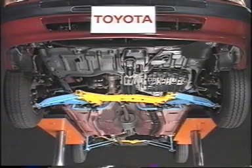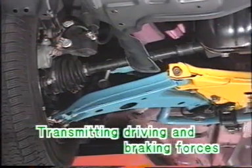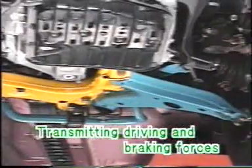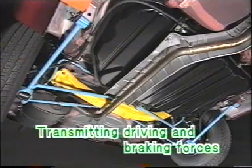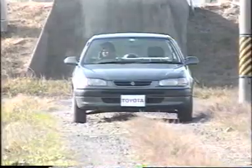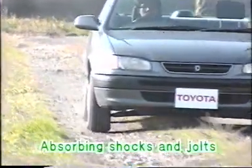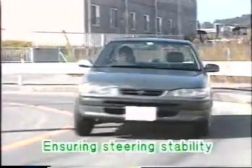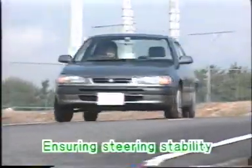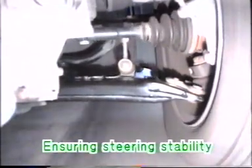The suspension's first function is to transmit the driving force generated by the driving wheels, as well as the braking force generated by each wheel, to the body, while maintaining the proper position of the axle. Its second function is to absorb the shocks and jolts received from the road surface to make the ride more comfortable. The third function is to stabilize the vehicle during driving by ensuring that the wheels follow irregularities in the road surface at all times to improve steering stability.